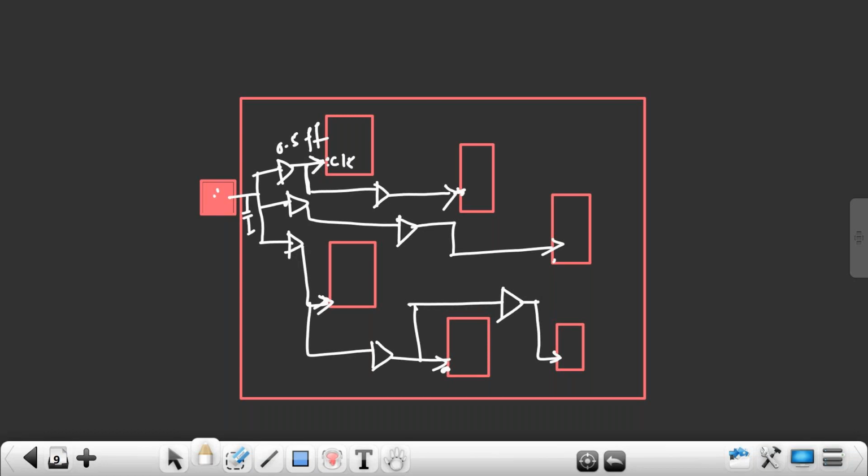If net length is more, again the capacitance will increase. Even metal has inbuilt capacitance. If more metal length, more capacitance. To break the net length, I should use what? Buffer. So that this clock transition is within some limit like this, and I will have minimum on time and minimum off time. For that reason, we have to build a clock tree. This is a clock tree, which I have built using what? Buffers.